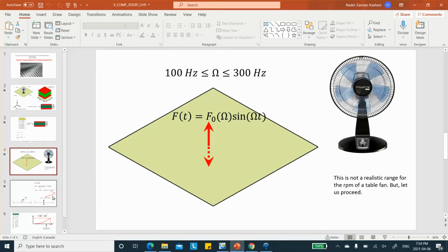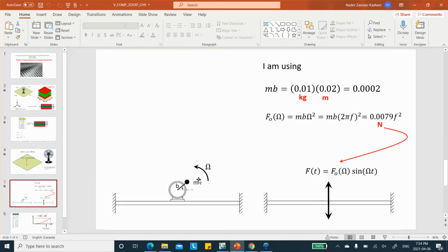If you look at your vibrations material, you see that if you have a mass that is a distance, say b, from some center of rotation, and this is turning at the angular velocity omega, the centrifugal force is m b omega squared. So you notice that this centrifugal force, because it's turning, is actually exerting a sinusoidal load in the vertical direction. It's going to be right here.